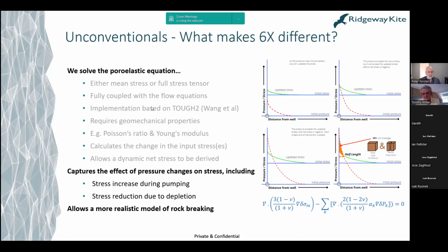I think the answer to this one is yes, in that if you've got a very shallow formation, you're at liberty to define your initial stress state such that you end up with horizontal fractures. So we would then end up with enhanced permeability in X and Y and not in Z, if you see what I mean, which I think you could think of as bedding planes having been lifted.